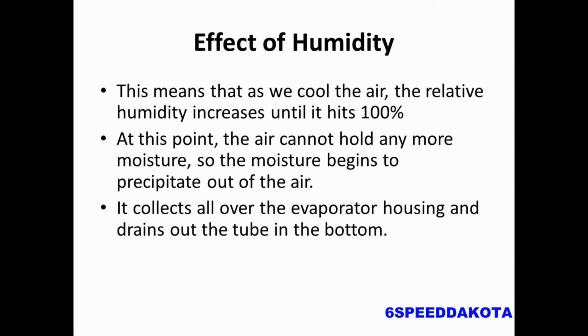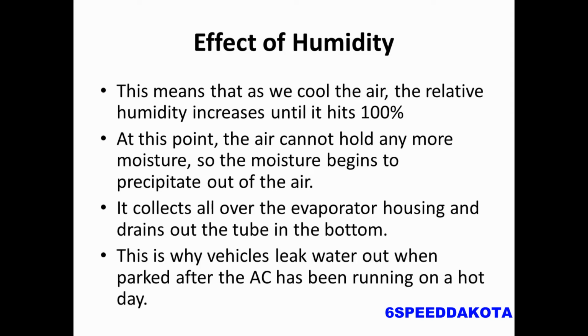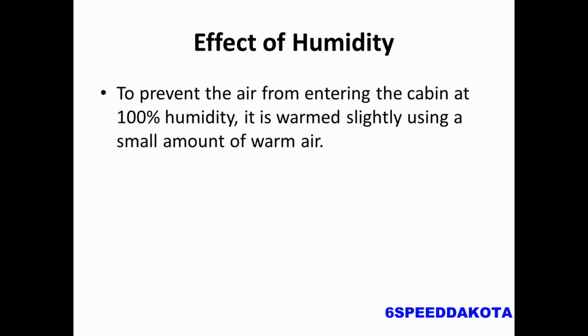So it collects all over the evaporator housing, and it ends up draining down a tube in the bottom of the evaporator. Have you ever seen a vehicle parked out on the road on a hot day that's had its AC running? You can see it dripping water out of the bottom. That's because of the dehumidification effect.